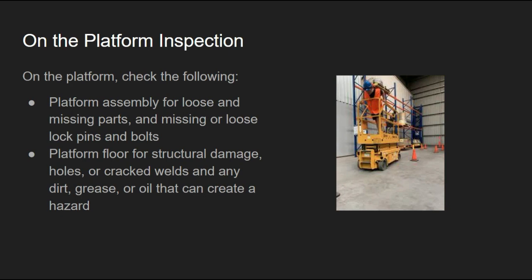On the platform, check for the following. Platform assembly for loose and missing parts and missing or loose lock pins and bolts. Platform floor for structural damage, holes, or cracked welds, and any dirt, grease, or oil that can create a hazard.